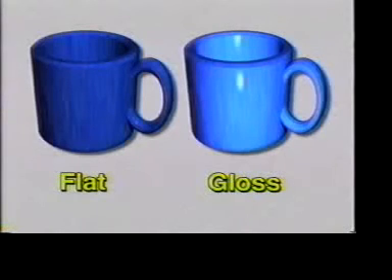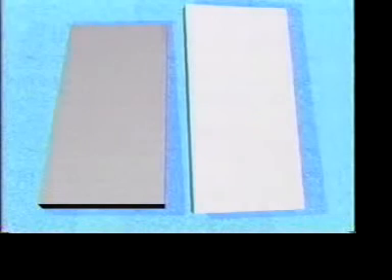If, on the other hand, the specular reflection is included in what you see, it will make the glossier sample appear to be lighter. These gray samples, shown here under laboratory daylight, were created using the same formula in base paints of differing gloss, flat on the left and high gloss on the right. The color match is close when the samples are held and viewed in a way that excludes the specular reflection from view. But when the angle is changed to the mirror or specular angle, the additional reflection from the high gloss sample lightens its appearance considerably. Same colorant formula, different gloss of the base paints.